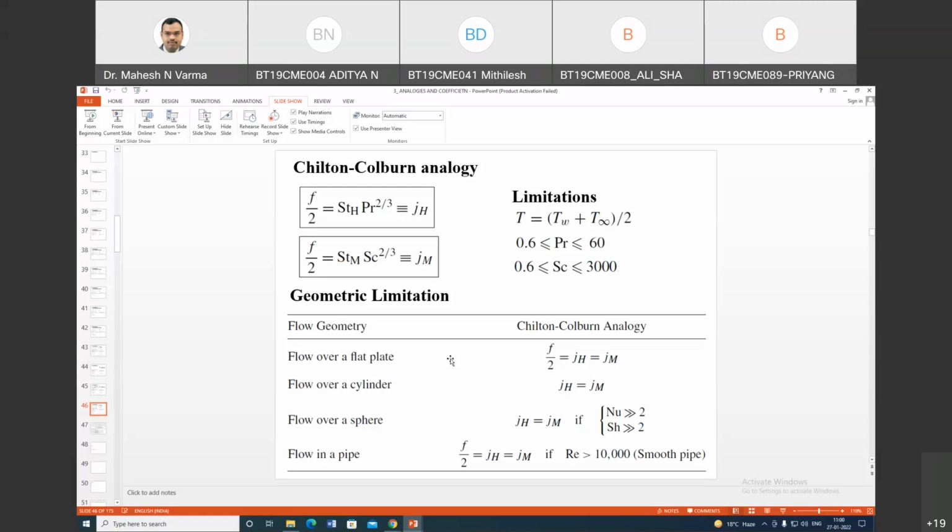Look, we are discussing interface flux. Interface flux means the heat transfer from the wall to the liquid. So the first layer is coming into the picture. What is the velocity at the first layer? It is 0. I am not adding heat from somewhere else, nor adding heat directly in the second layer. When in the first layer there is no velocity, how can there be a convective term?